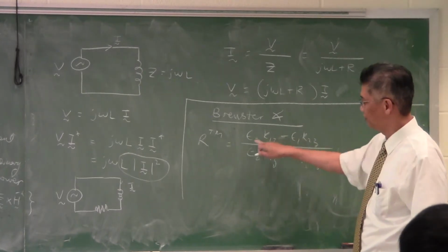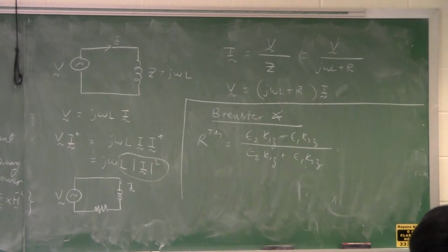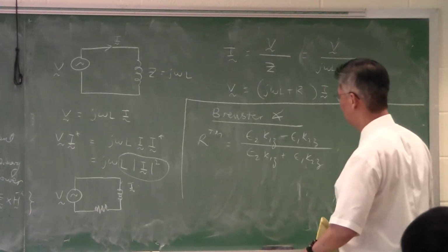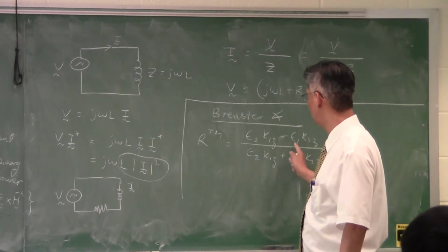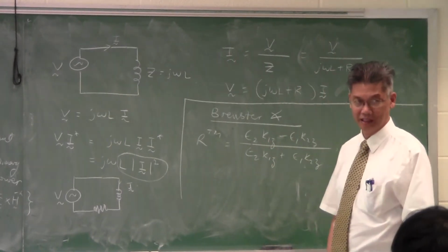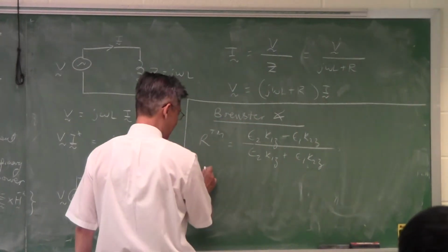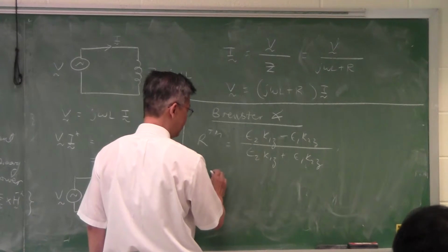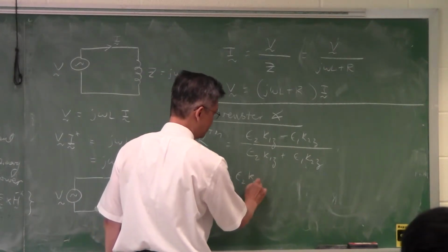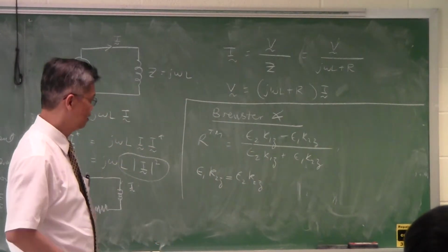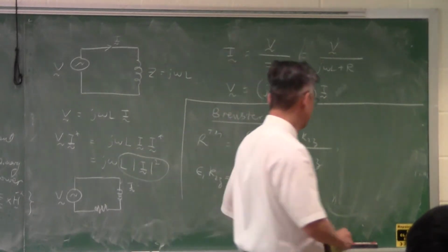For R TE, epsilon is usually replaced with mu, but most materials are non-magnetic in this world, so it's not easily observed for TE polarization, but quite prevalent for TM polarization, because most materials have epsilon 1 not equal to epsilon 2, but it could occur that there will be a certain angle of incidence where these are equal to each other. If that is true, then the reflection coefficient will be equal to 0.